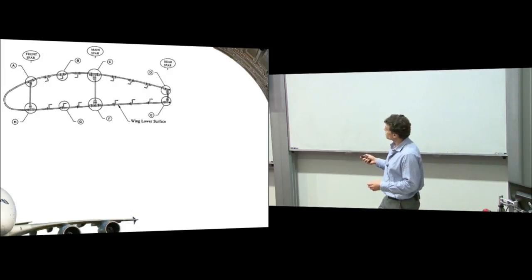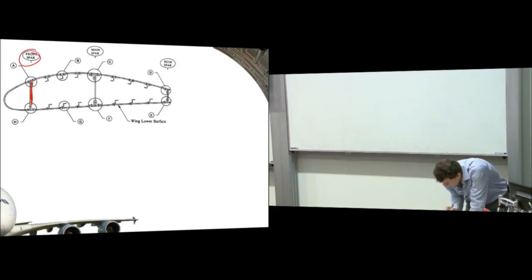If we have a bit of structure like this, we have our front spar, and these are all labelled on the diagram if you want to look along here, a main spar, and in this case we've actually got a 3-spar configuration, so there's a rear spar as well. And we have these little bits of built-up structure called spar caps at the end of each spar. We have Z stringers on the tensile surface and J stringers on the compressive surface.